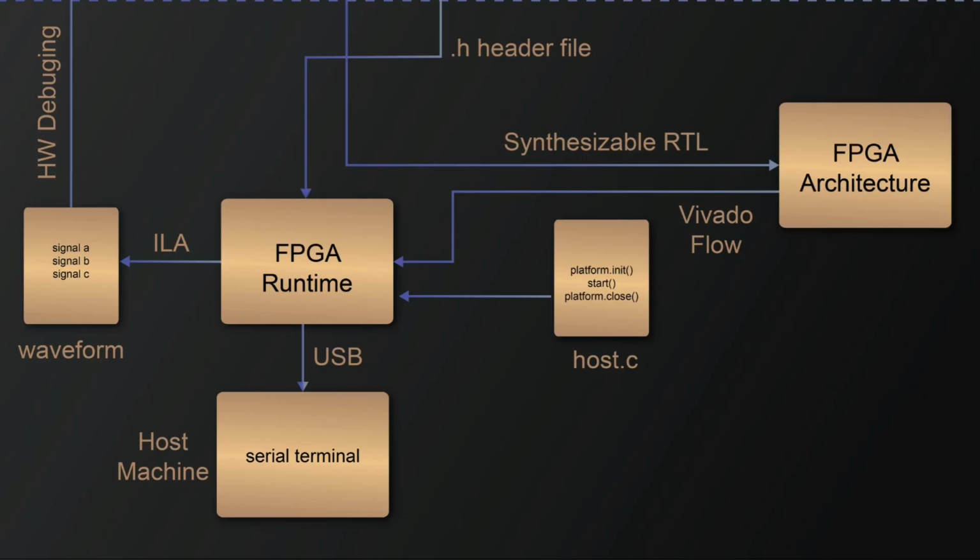Finally, we deploy the design to FPGA using the Vivado flow. At runtime, a serial terminal and USB interface allow user interaction, while the integrated logic analyzer helps capture on-chip signal transitions, enabling real-time debugging and in-depth validation of our hardware.